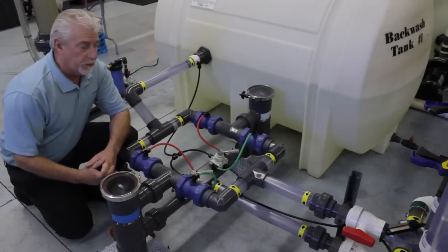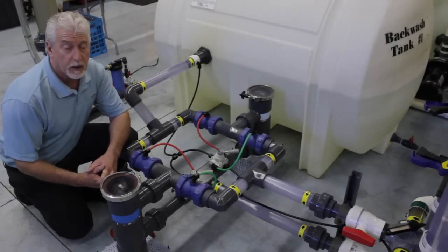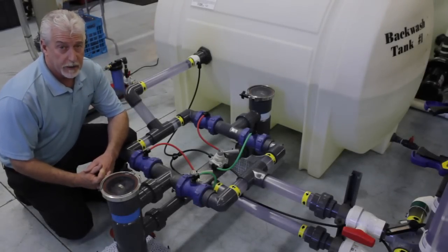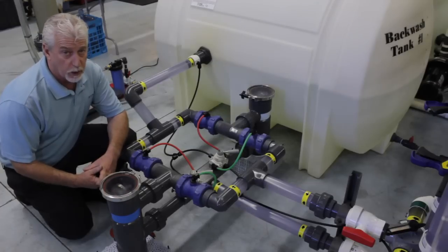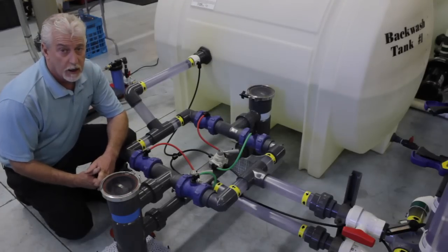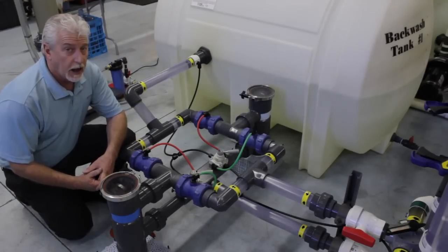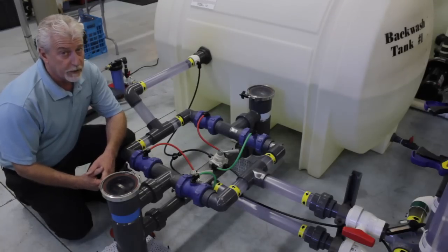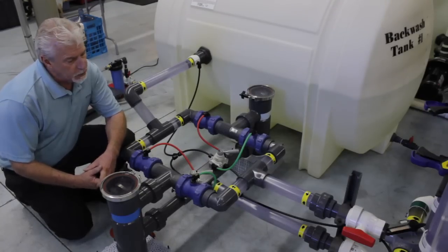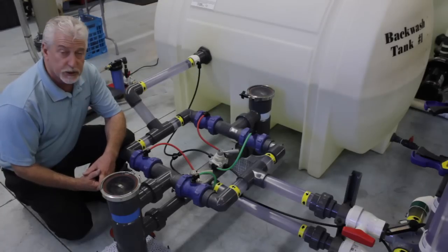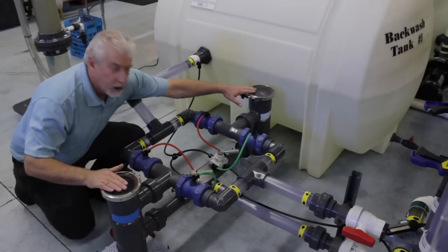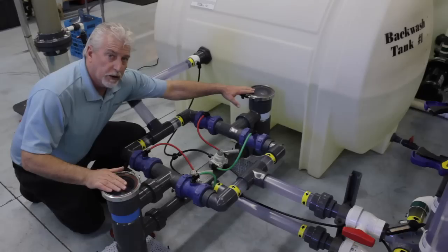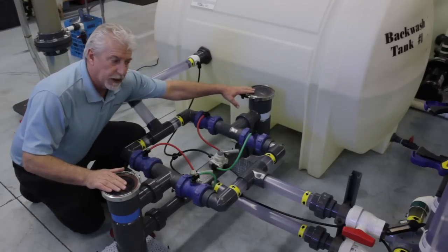Radial flow filters work best in banked installations, multiple filters, and let them backwash sequentially with what we call pulse backwash. They backwash very fast, and when there's a multiple installation, they actually use the clean water from the other filters that are still online. So we have a demonstration set up here with 2 conventional filters that can backwash each other with clean water from the one that's still online.